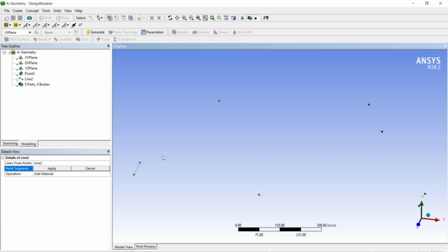For example, if one line is made up of a square beam, and the next line is going to be made of a circular beam, we cannot generate these two lines in a single line file. So if we have multiple cross sections, you need to select the points separately, but if you have the same cross section, you can select them in a single group.